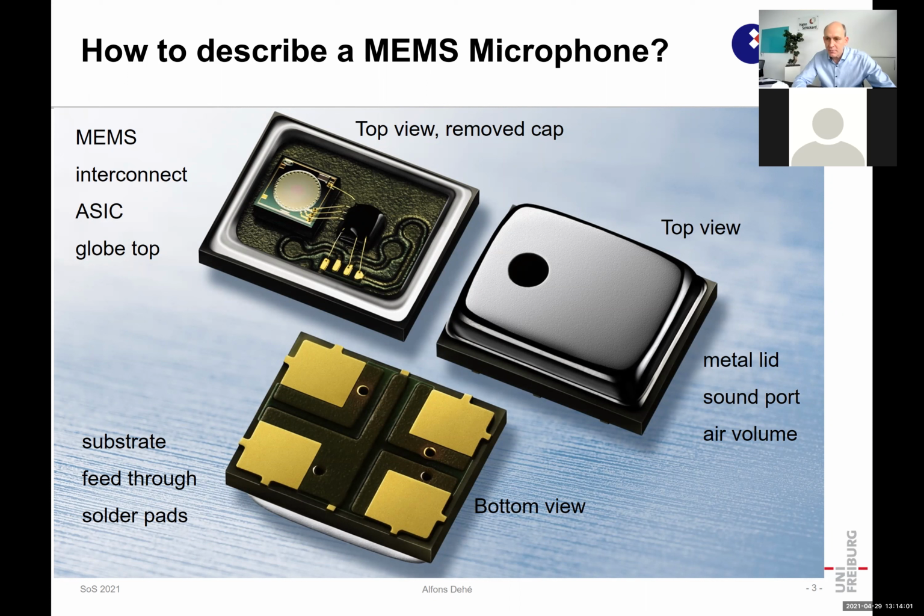You will have a chance maybe later on to see them in real. It's a transducer from mechanical devices. It's an ASIC, with interconnects in between, assembled on a small PCB, which gets a lid out of metal and a sound port. And we see already that all this covers mechanical domain, acoustical domain, then transduction again to a mechanical system into electrics, and finally to the output nodes.